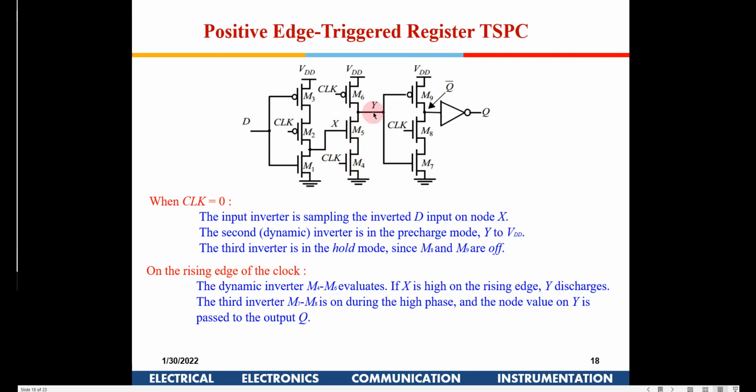So that is what happens in a dynamic circuit, right? Whenever Y is pre-charged to 1, depending on the logic, it will either be discharged to 0 or that 1 remains here. So here also, it is going to be discharged to 0 in case X is 1, otherwise it continues to remain at 1 out here, right? Now this clock is going to be switched on here, so this becomes an inverter. So Y bar, and then again this will be available here, so the D will be available here.